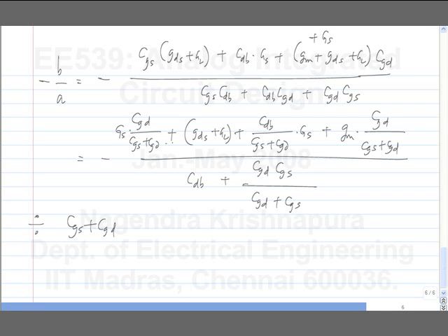So what is the interpretation of this answer? The GM is very high, we can ignore the other two terms in the numerator. Okay. And what we say is the GM by the capacitive coupling is being seen at the output, and this is a net step at the output. Do we get the GS CGD term here in the numerator? We do. We do get it? Okay, that's fine.